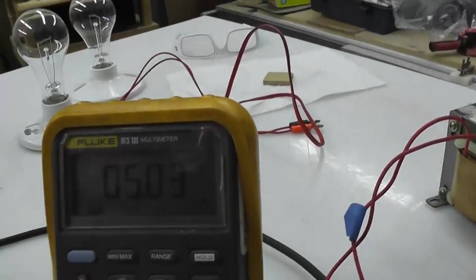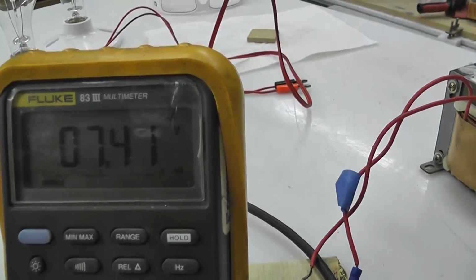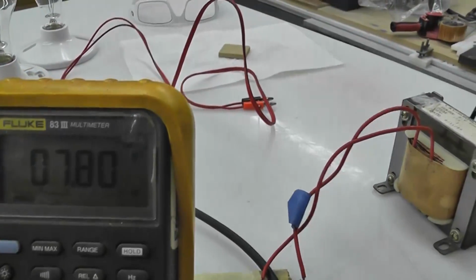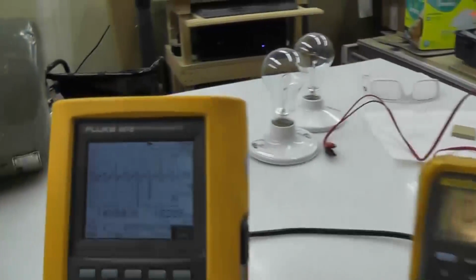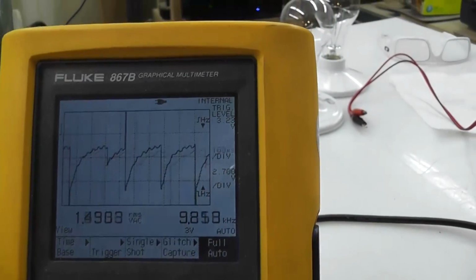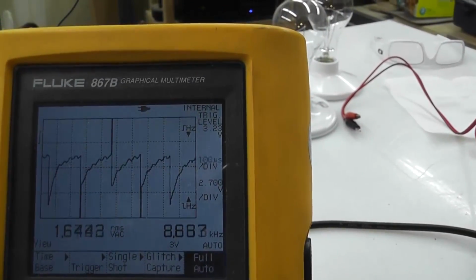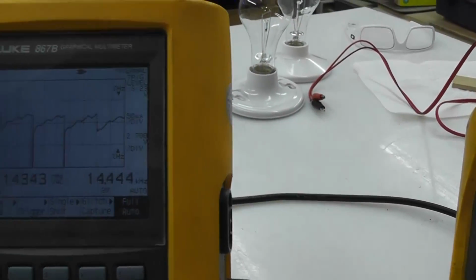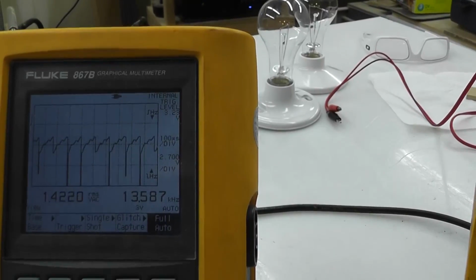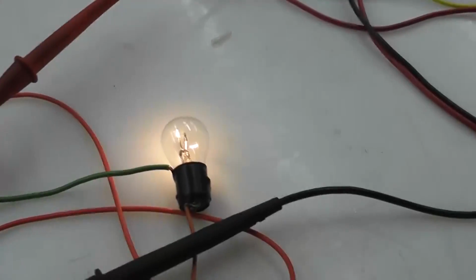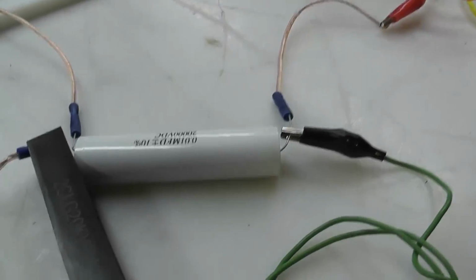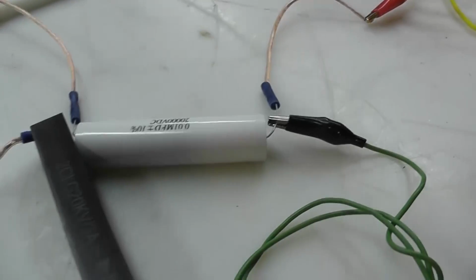And here's what this meter says the voltage is. Now you can see when it squeals really loud it goes up actually, which is interesting. And here's what you see over here. So we got 1500, 1600 volts at 10-ish kilohertz, so it keeps jumping around. Anyway, light bulb, pretty dim. So let's reconnect the other capacitor in there with the same situation.